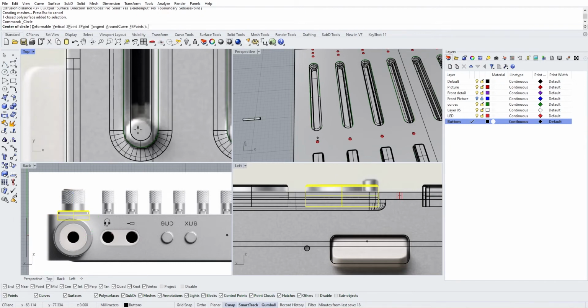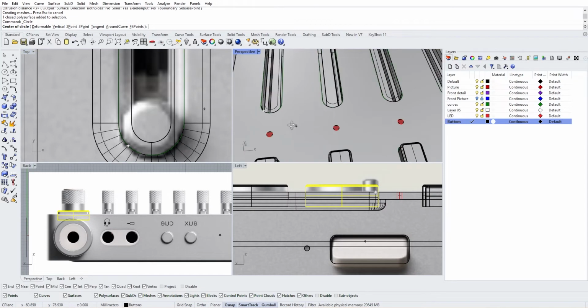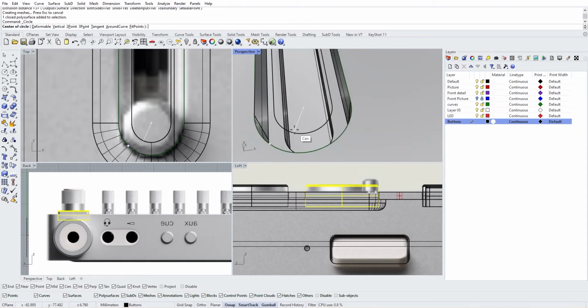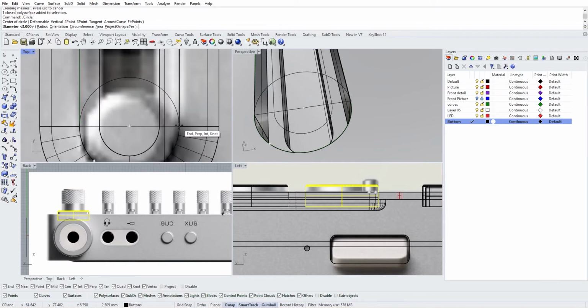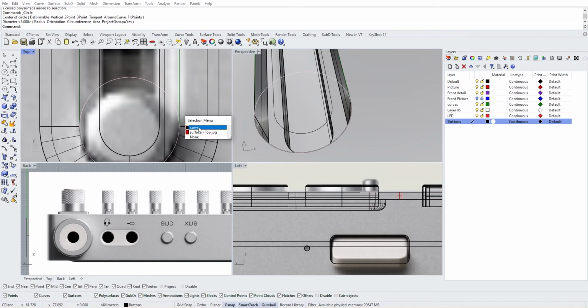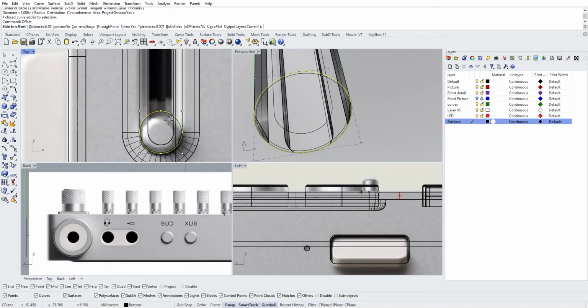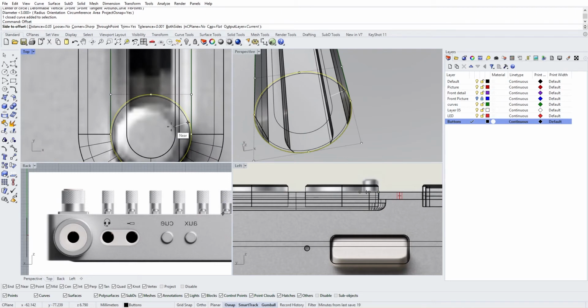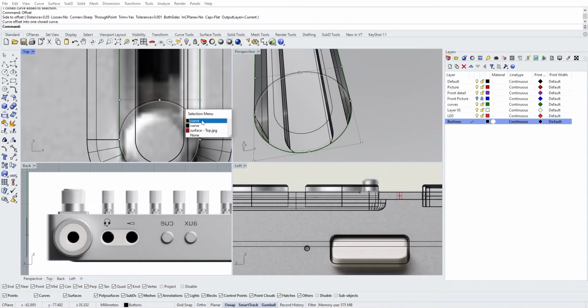So create a circle that starts in the middle of this piece here, and then do it exactly at the correct size, and we're going to the correct size of the outer boundary, and then we're going to offset it. So offset of, let's say, yeah, 0.5 again, like this here.